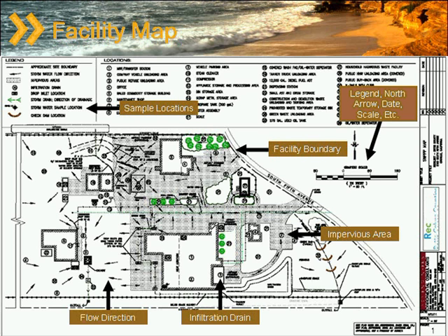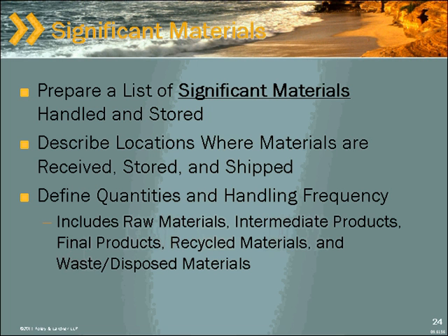But one grab sample of qualifying storm events per facility or per drainage area is likely to remain as the minimum requirement. But going beyond that, there may be a lot of reasons to do that, and that largely, I think, will end up being left to the SWPPP developer. So there's some room for flexibility in the monitoring sampling program. I believe, without certainty, that will be the case when the permit actually gets out in draft. So grabs or something else.